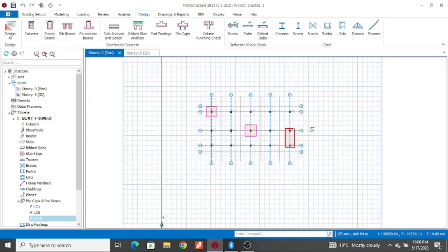Also sometimes the axial loads are very high and you have a lot of moments in your foundation. You might want to use a raft or a mat foundation. So in the use of a mat foundation, you have to start modeling again. You model now on this floor, you can do your beams here, and then you do slabs. You model them as normal slabs, and then if you want to use this software, use finite elements for its analysis, and you also design it.